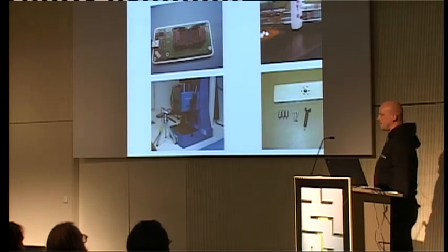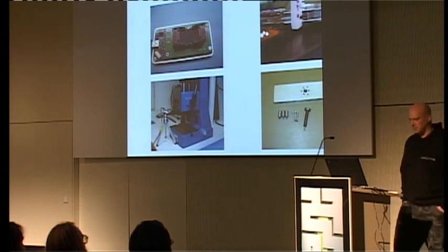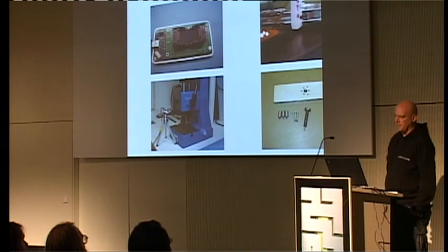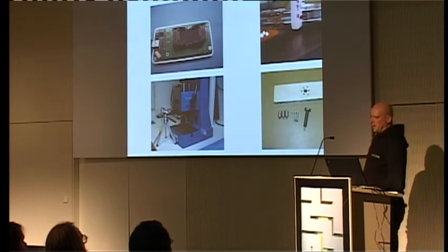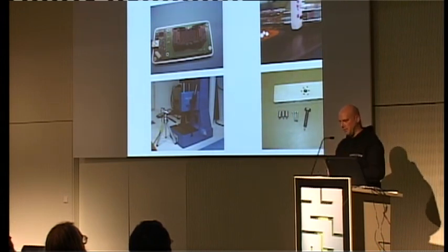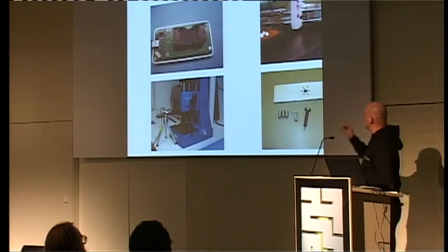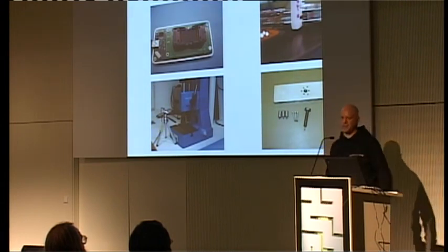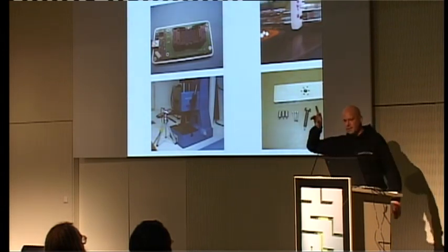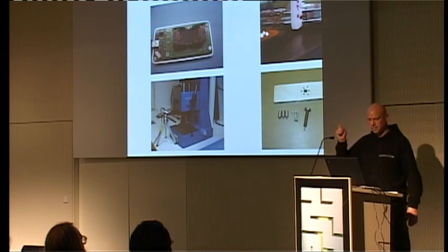Top right, you have something we call a head lifter. That's a specifically machined tool that we made ourselves. We have some software that works by parameters taken from the measurements, from the dimensions of the hard drive. So we disassemble the hard drive, measure the dimensions, feed that into a program, and that gives us the proper head lifter for the specific hard drive. That's what comes out of the process. The material is polyoxymethylene.